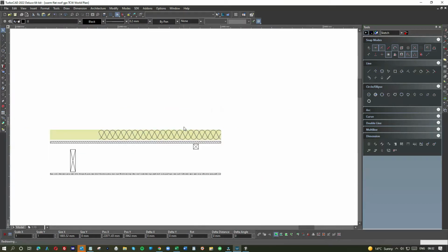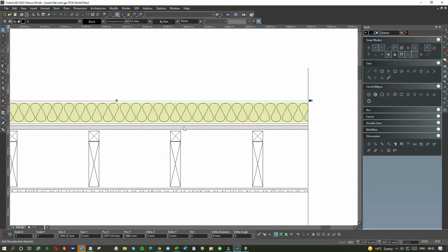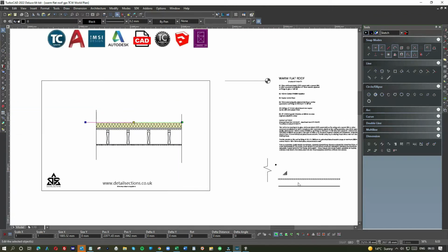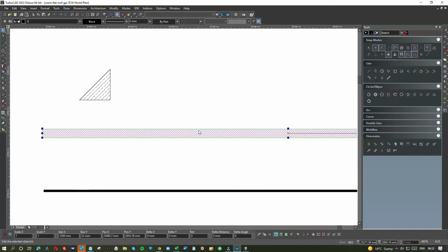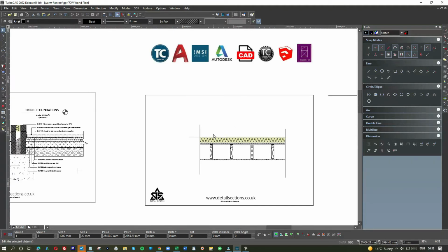I'll tidy up the ends in a minute. So then we're getting there. So remember, plasterboard, vapor barrier, joist, fairings, plywood, that's 18mm plywood, that's exterior plywood by the way, it's not the cheap stuff. And then it's vapor barrier, insulation, and vapor barrier again, so that it's basically sealed. And then on top of that we have the roof finish, well not the roof finish, but the top timber. So the top timber again is plywood, but this one's a little thicker. This is 22mm.